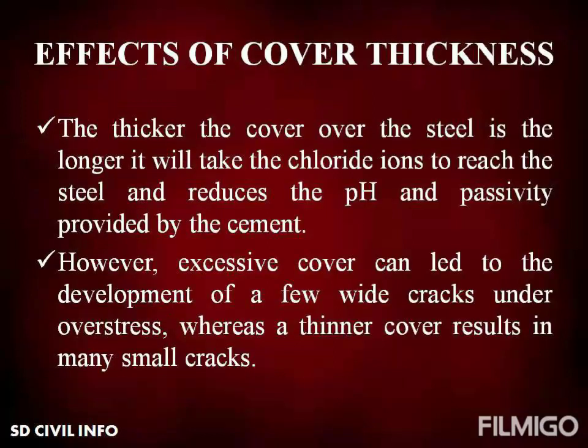The next one is, what are the effects of cover thickness? If the cover over the steel is thicker, then it takes a longer period for the chloride ions to reach the steel, which delays the reduction of pH and passivity provided by the cement. However, excessive cover can lead to the development of a few wide cracks under overstress, whereas a thinner cover may result in many small cracks.